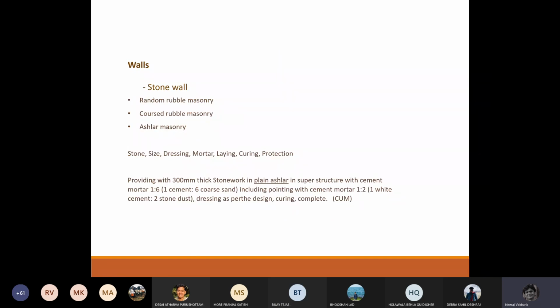So this is the part of wall. Now again, your work is not just done here after calculating the length, breadth and depth with the volume. There are also some deductions which you have to do, which would be for doors, windows, arch, skylight, whatever opening you provide. Those items would be deducted.